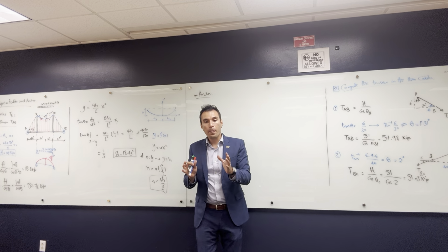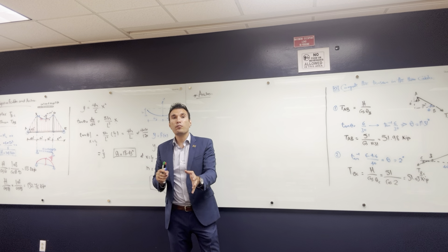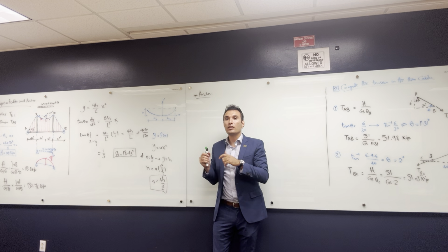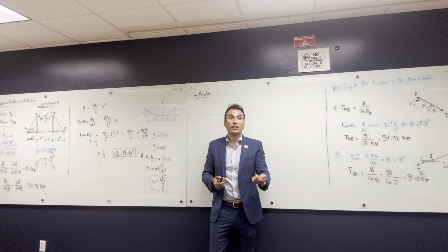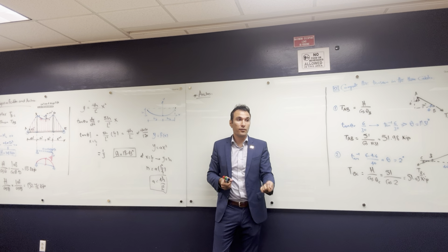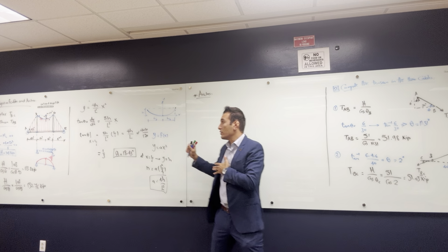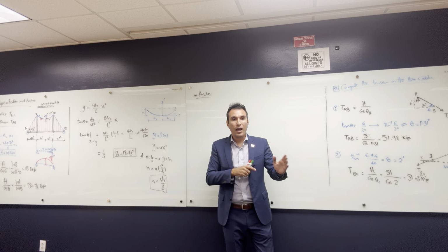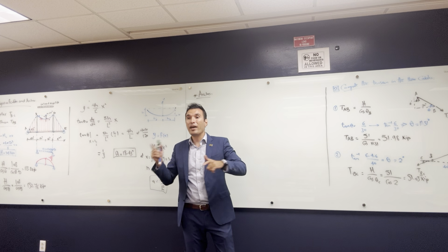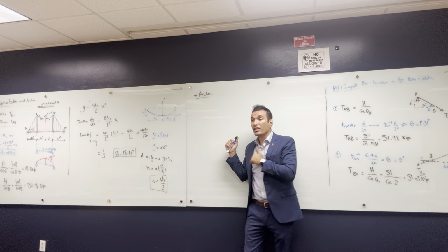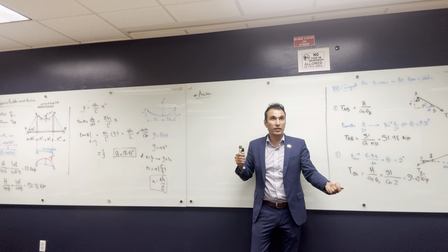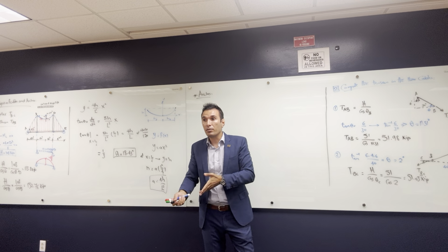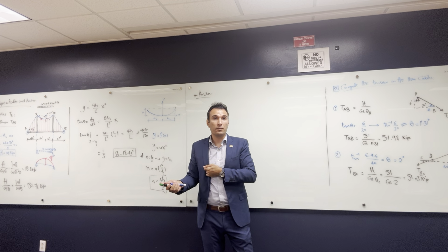And the way that you are a better engineer, the way that you make the bending moment less, is to try to get rid of the bending moments. Okay? But these systems to build, it needs lots of efficient labor. So that's very expensive. So you need to justify this. If you are gonna use people to build a cable system or an arch system, you have to pay more for labor to save material. So you need to balance between both of them. These systems are gonna save you in material, but the labor is gonna be more expensive. However, with simple beams or the regular systems, the labor is cheap and the system is a little bit expensive, okay?